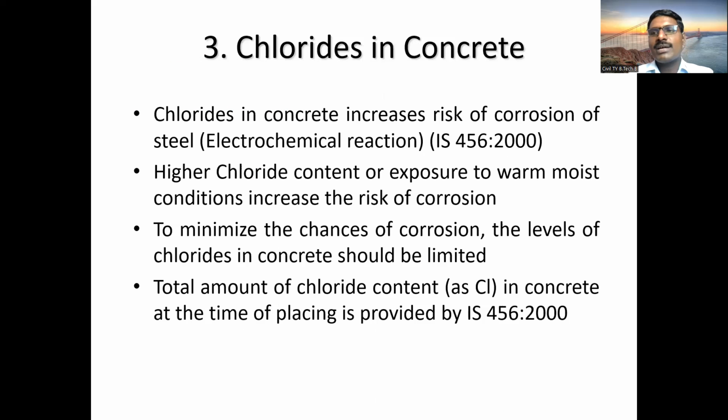So then the chloride content in the concrete. Chloride in concrete increases the risk of corrosion of steel. That is as per the IS 456 2000. So if the chloride content increases, or chloride content comes from nearby, chloride attack will occur on the concrete.